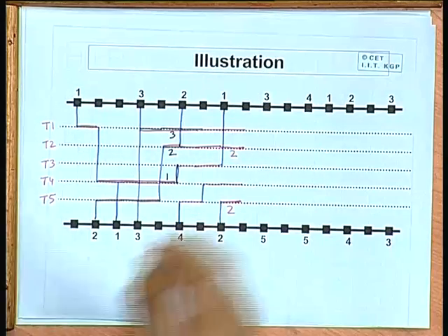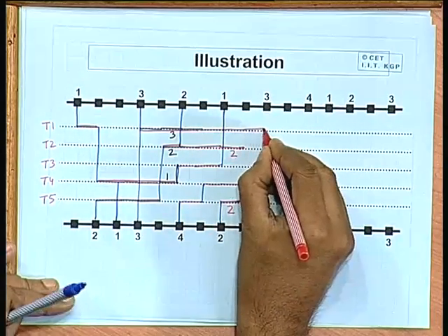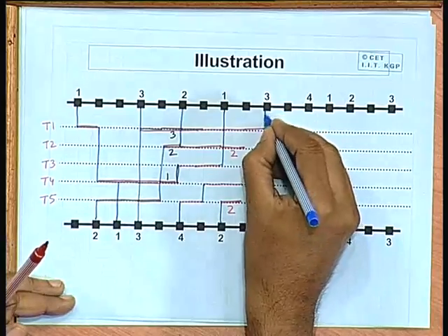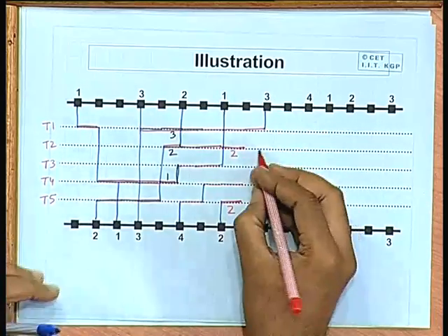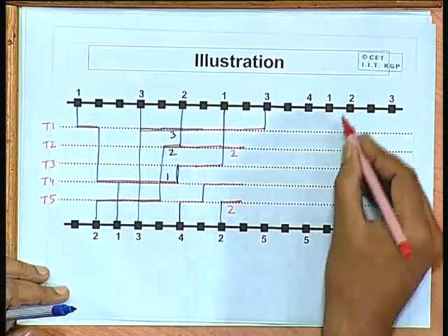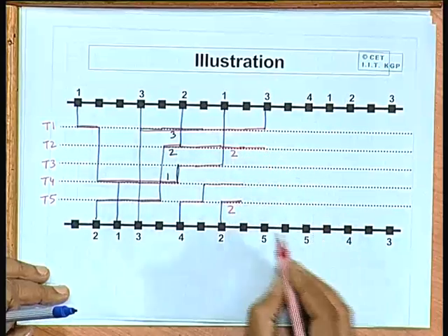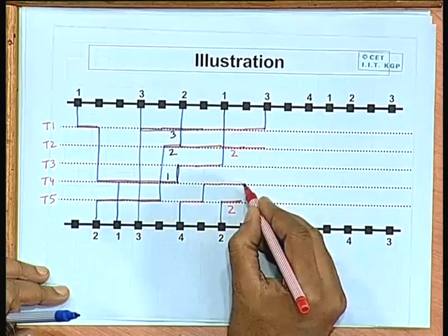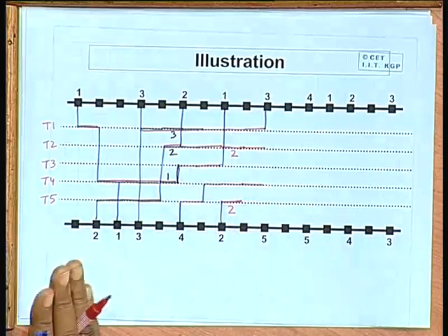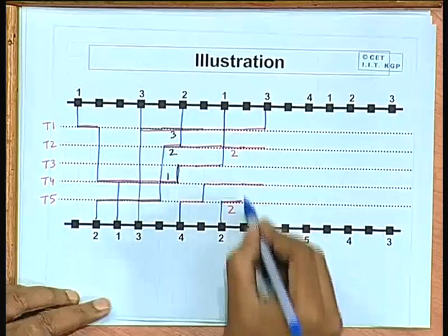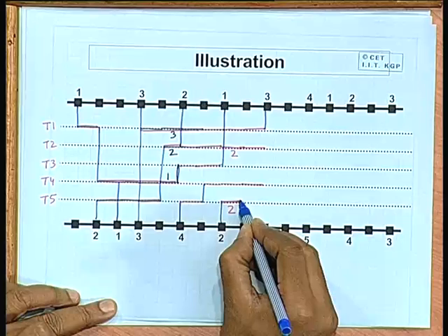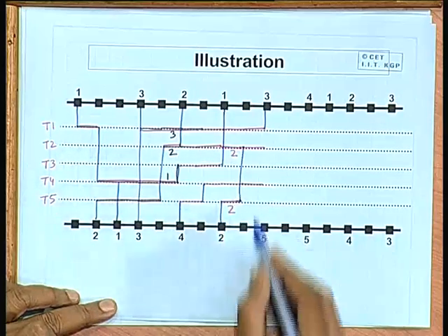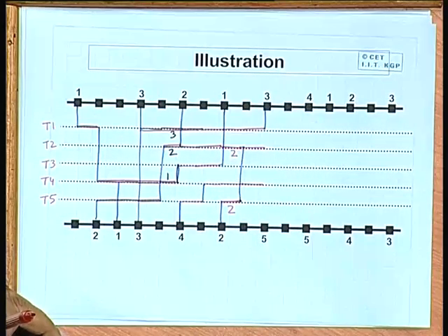So, similarly, the next column 3 will proceed and a connection will be made. 2 also will proceed, 2 has a terminal on top, 2 will proceed. Net 4 will also proceed, and 2 you can split, you can merge the split nets here itself, there is no conflict. So, 2 and 2 get connected here. So, in this way it will continue.